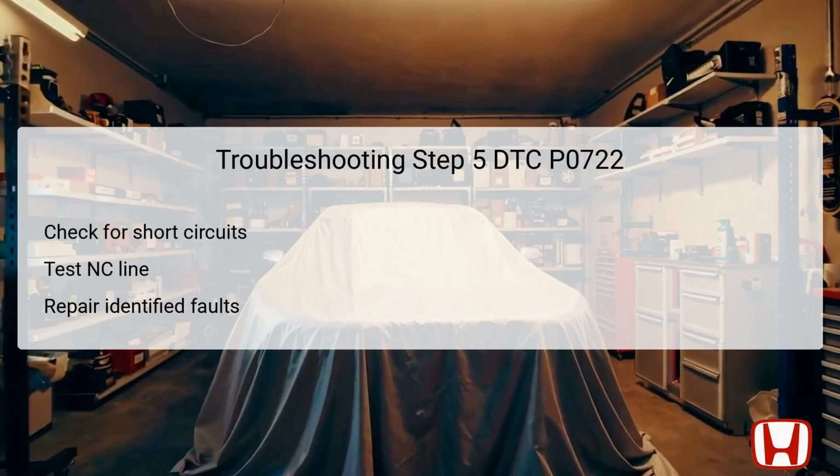To initiate this process, turn the ignition switch to lock and use the HDS to jump the SCS service check switch line, which is a required procedure for running diagnostics. Once the SCS line is jumped, disconnect the PCM connector B to access the relevant wiring. At this point, measure continuity between the NC pin on the output shaft sensor connector and body ground.